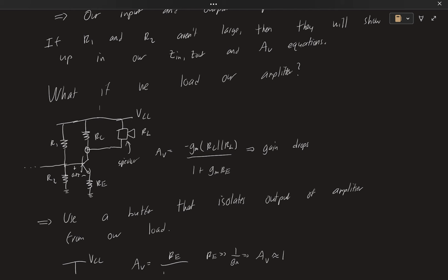If RL was infinity, if we have RC parallel infinity, things in parallel prefer the smaller ones to the output. So this is going to just be RC, right? That gets us to our equation from before, as if we didn't even have that speaker to begin with.